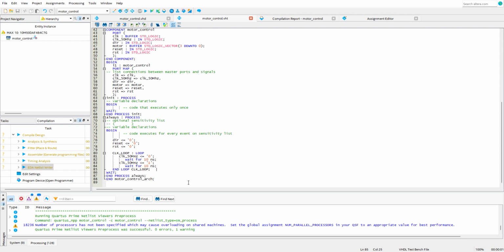Now, the loop then continues in execution, repeating the process to generate subsequent clock pulses. As there are no exit conditions specified within the loop, it iterates indefinitely, continuously producing a square wave clock signal with a period of 20 nanoseconds, with 10 nanoseconds low and 10 nanoseconds high.